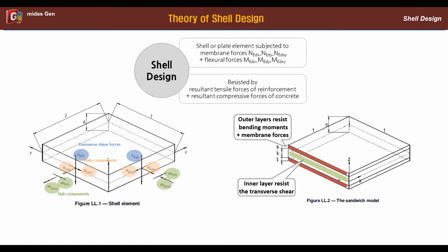I'm going to introduce the theory of shell design, that is sandwich panel theory. The program designs shells as per sandwich panel theory. One of the practical approaches is the report by Brondum-Nielsen. This work deals with the shell element as if it were a sandwich element composed of 3 layers.